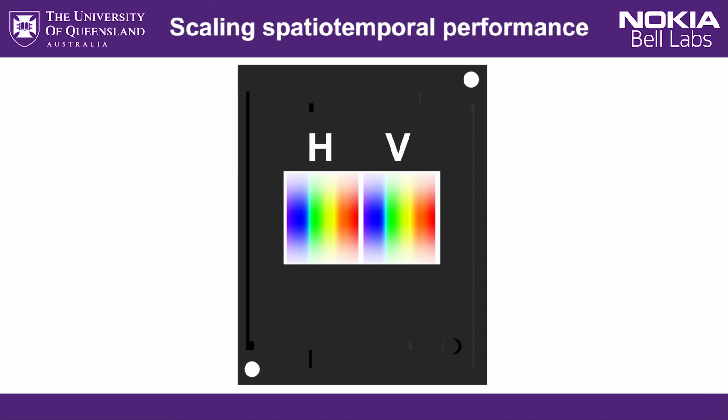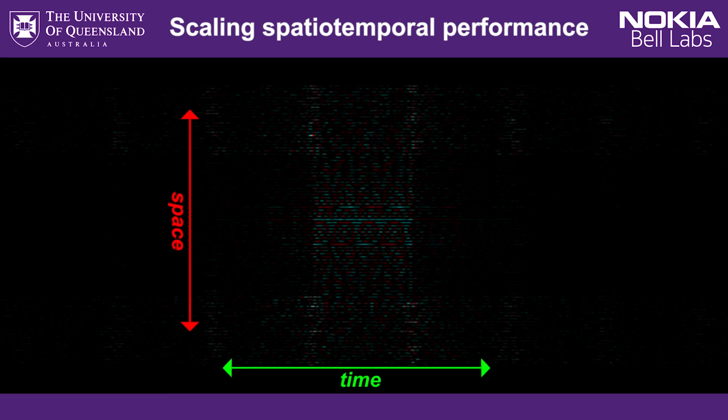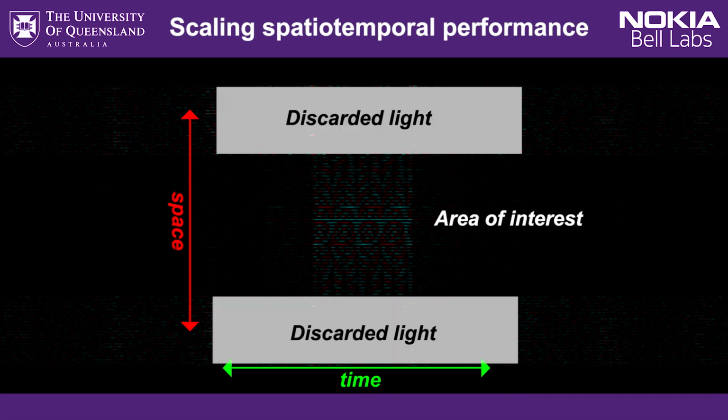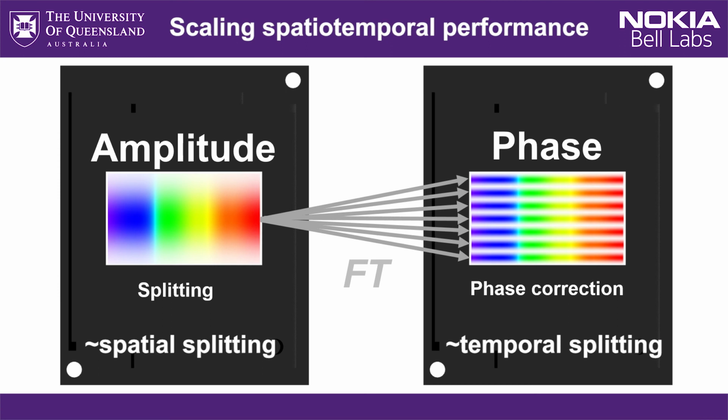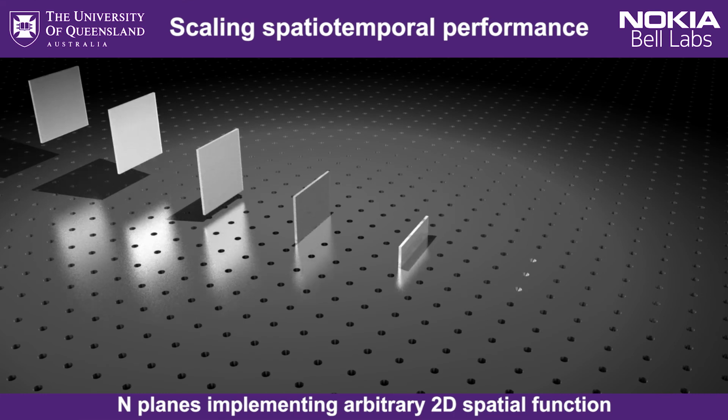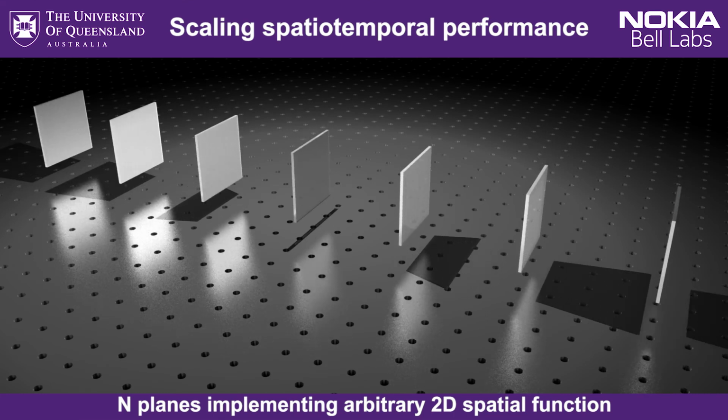In our design, we do a 45-way split for each polarization using a single SLM. That single SLM has to make each spot have the correct amplitude and the correct phase. And that also introduces additional loss because it necessitates some discarding of light, as is the case in general when you're trying to match amplitude and phase using a single phase mask. An alternative is to use two SLMs. The first does the amplitude split the best it can, the second fixes the phase of all the modes. And then you could also abstract that even further to make it something more like an MPLC type system, not strictly amplitude and phase in the two planes, but just n planes of phase manipulation which implement a given transformation. Another way to increase the number of addressable degrees of freedom is by spreading the load amongst multiple SLMs.